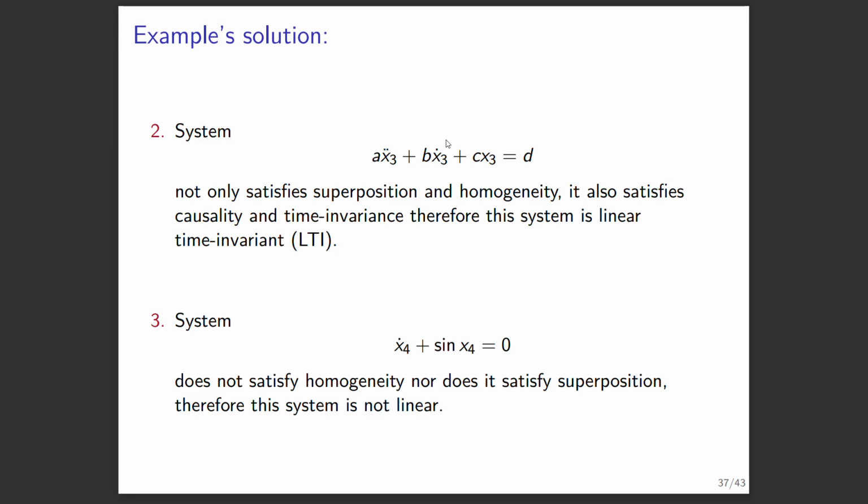How about this system? I have a system with this differential equation, its transfer function, describing the dynamics. It does satisfy the superposition. You can replace x with ax, and also you can check it's homogeneous. It also satisfies the other two additional conditions of time invariance and causality. So this system is linear. And in general, every ordinary differential equation that we study is linear and time invariant.